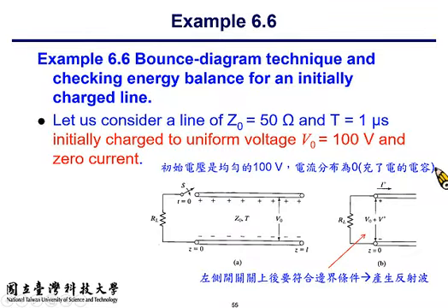And at this moment, the transmission line can be regarded as a capacitor. Why? Because you observe a voltage difference on this structure and no current. So at this very moment, the transmission line behaves like a charged-up capacitor. And the energy is stored in terms of electric field because you only observe a non-zero voltage. On the other hand, the current on the transmission line is 0 everywhere.